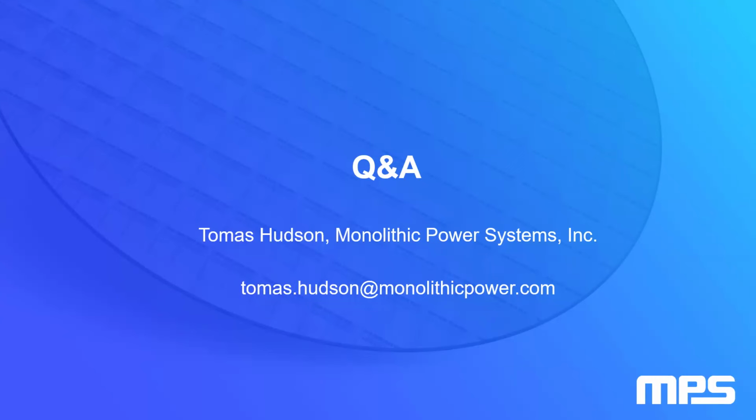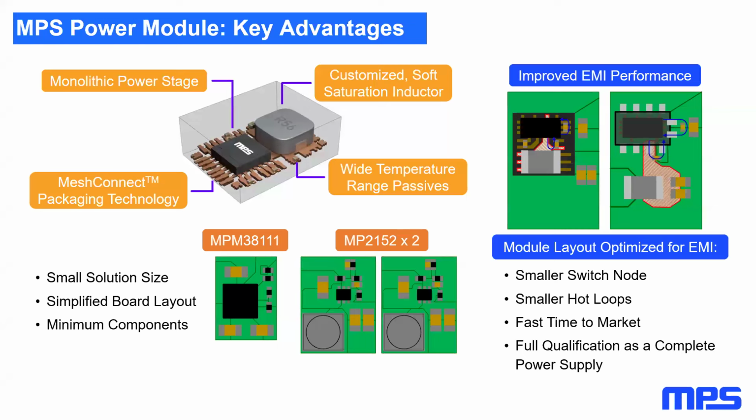It depends on the fabrication process, but for example, we do have open frame modules on a PCB. But the ones that I was mentioning today, for example, the 3695-100, those inductors are placed straight onto the lead frame and then molded in the same package. So that's one single block.